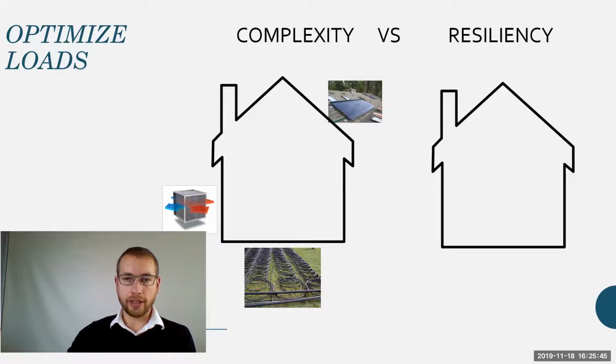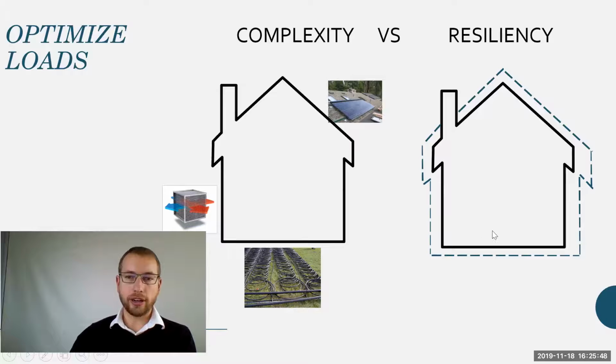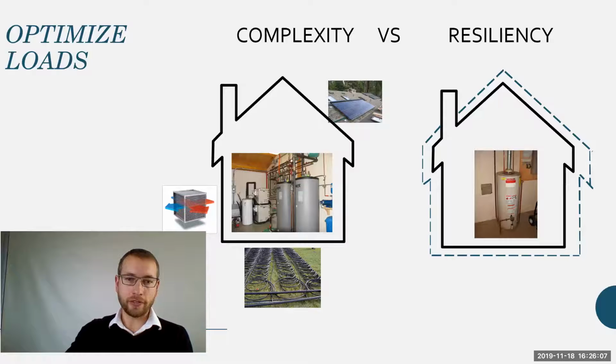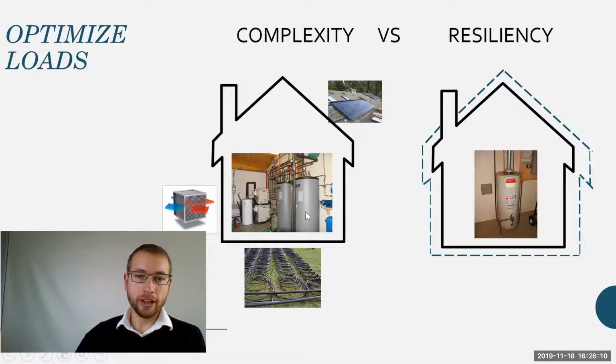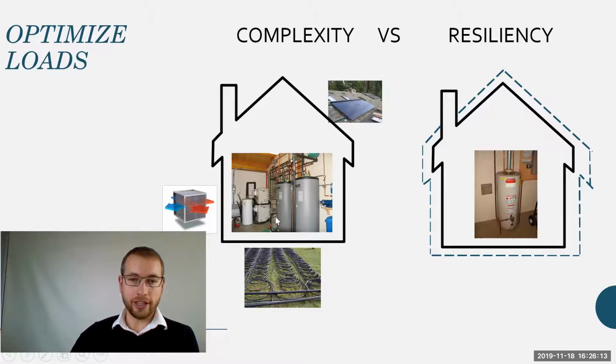Whereas if we look at simply hyper-insulating our envelope, tightening up all the seals around everything, adding some attic insulation, insulating around the walls, maybe minimizing the amount of window exposure, we end up with a system that might use about the same amount of energy, even though it's using really old, boring, conventional systems to do that. But if you look inside, in our complex building, we might have a couple of different heat pumps, a heat exchanger, a whole lot of piping, whereas in our tight thermal envelope over here, we've got one much smaller, maybe a little less efficient, but much simpler system.